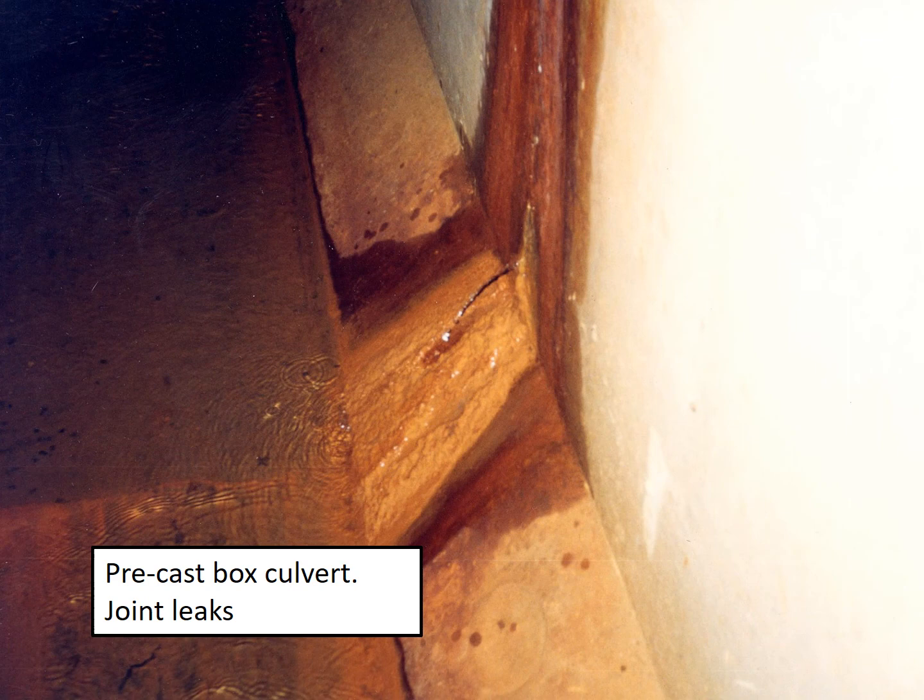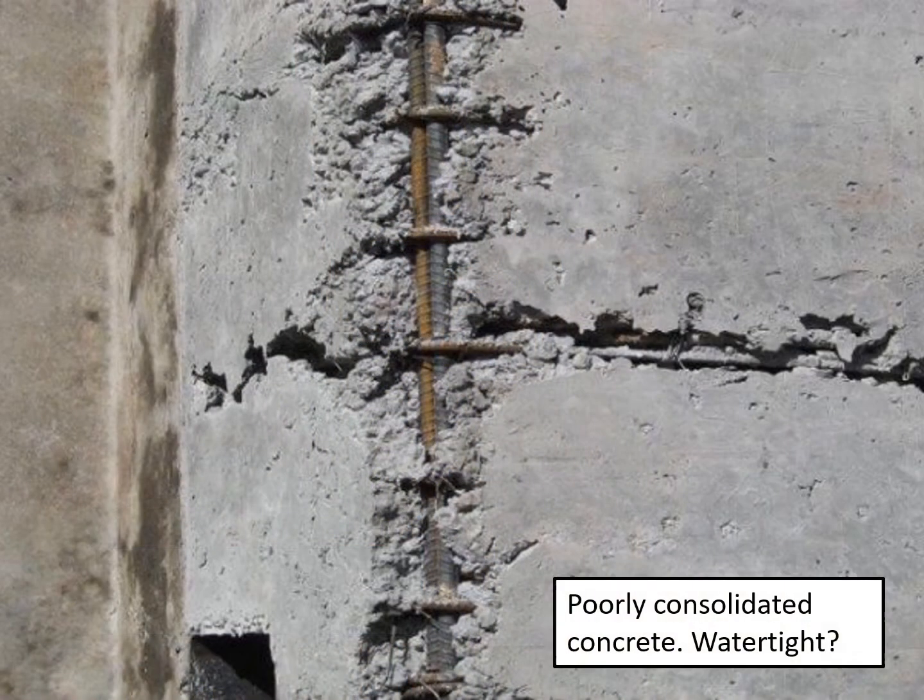Here's an example of a precast box culvert with a leaky joint and material deposition. And then of course here's a classic picture of some really horrible concrete work. We want to avoid this. Is this going to be watertight? Is this going to be a long-lasting structure if we've got this poor consolidation and shallow cover on reinforcing steel? It's not good for anybody. So that would be an example of something to avoid.